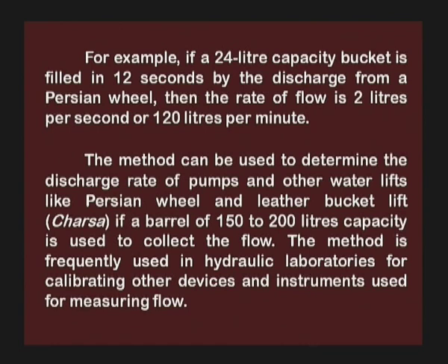The method can be used to determine the discharge rate of pumps and other water lifts like the Persian wheel and the leather bucket lift, that is Chadas, if a barrel of 150 to 200 liters capacity is used to collect the flow. The method is frequently used in hydraulic laboratories for calibrating other devices and instruments used for measuring flow.